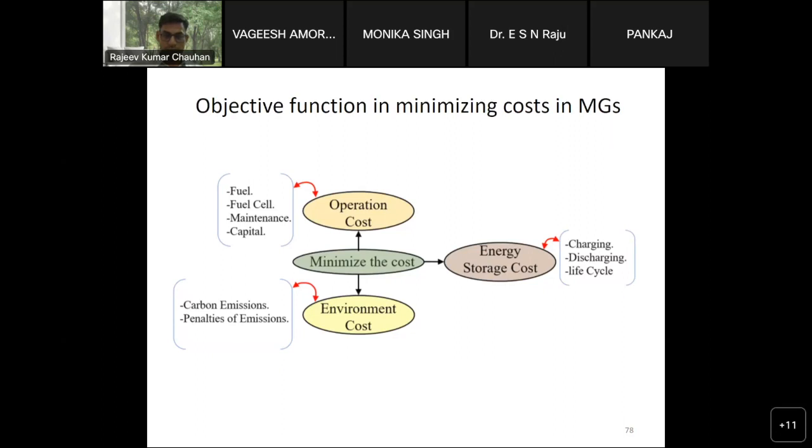See, how can a diesel generator be a storage system? A diesel generator is only the emergency generator. What I am trying to say is to use it in place of the battery storage system. No, that is not possible. With a diesel generator, you can supply the power, but you cannot store the excess power. When we are dealing with renewable energy resources like solar PV and wind, sometimes you may have more power generation from the solar PV. Where will you store that excess power if you are using the diesel generator?